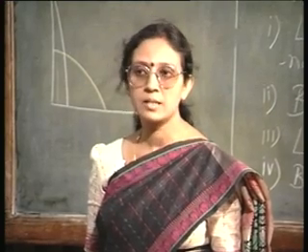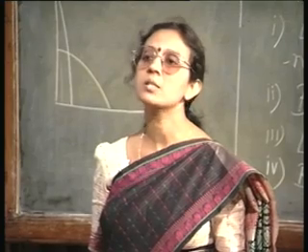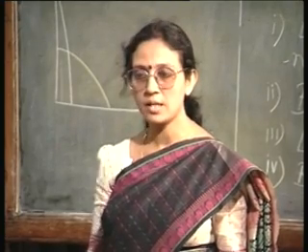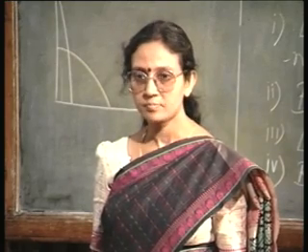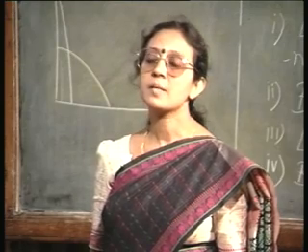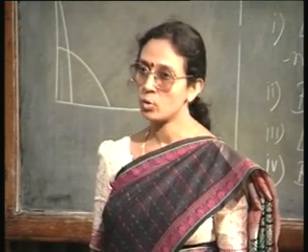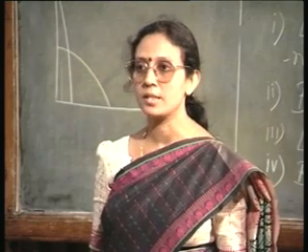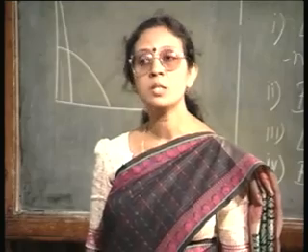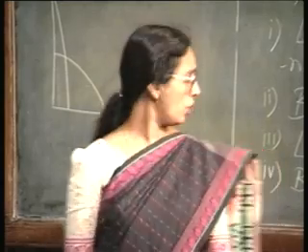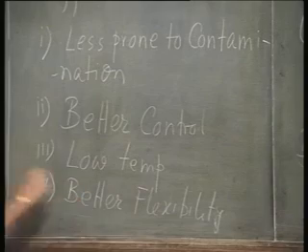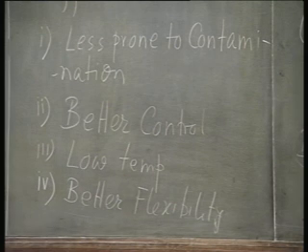I can adjust the energy so that the peak is somewhere inside the semiconductor, underneath the surface, not at the surface, right. At the same time, I can adjust the peak concentration. I am no longer governed by the solid solubility criteria. The peak concentration can be even in excess of the solid solubility limit. So, all these things you can put in better flexibility. There are various things one can do with ion implantation which is not possible with diffusion.